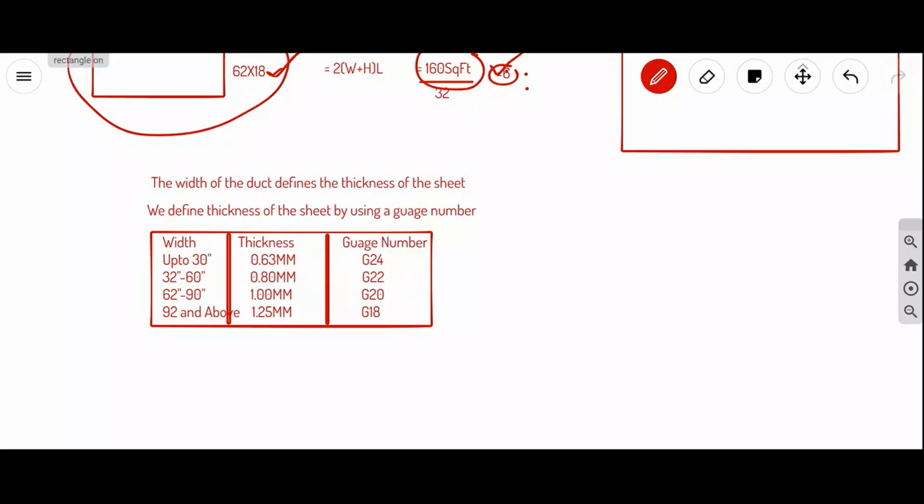And chilled water, thickness of insulation for chilled water is 40 mm, and thickness for hot water insulation is 60 mm, and insulation material is puff polyurethane foam. Okay, chilled water is 40 mm, whether it is a supply or return. 40 mm is fixed. Sorry, for hot water it is 60 mm. Hope you are clear with that, right? So still any doubts you have?